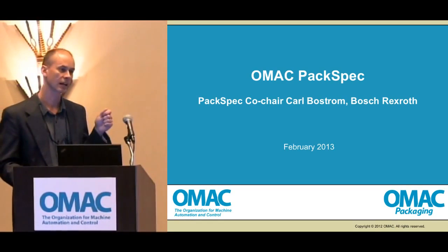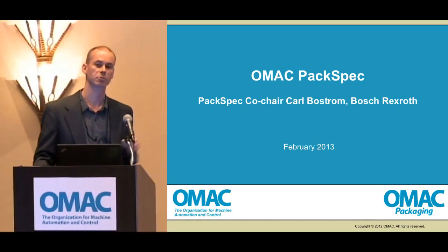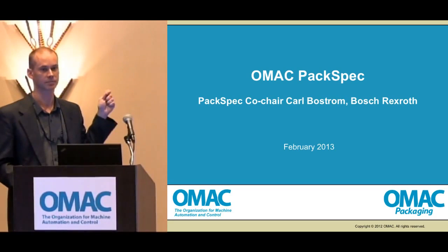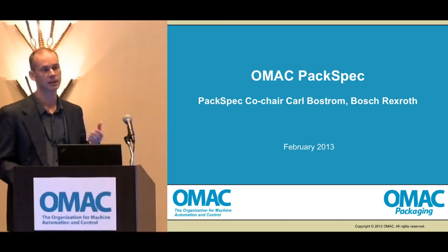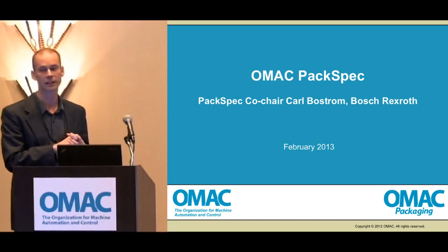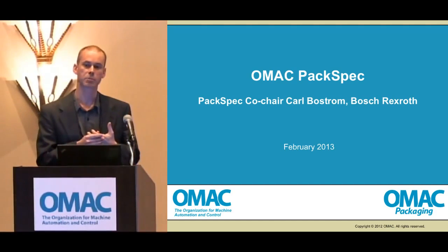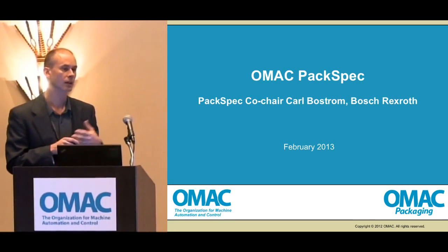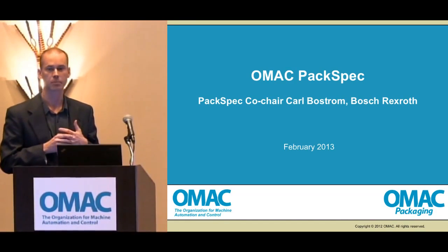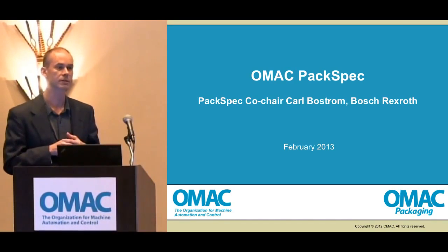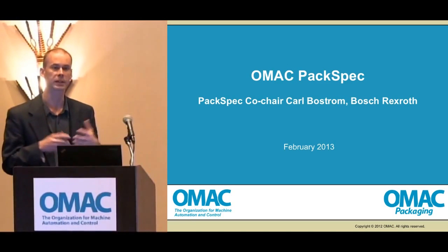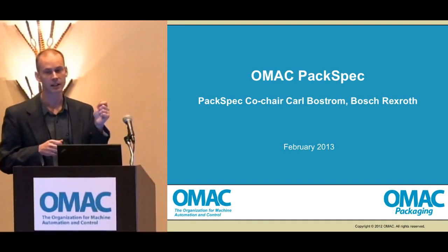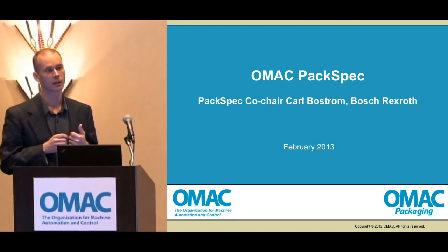We don't see that at any point in the future an end user will be simply able to say, give me PackML. There's more to it than that. The end user really needs to define exactly which pack tags he expects to see. In the base state model, he may expect to see certain states. He may not care about others, but there's a process there. It's much more than just saying, give me PackML.